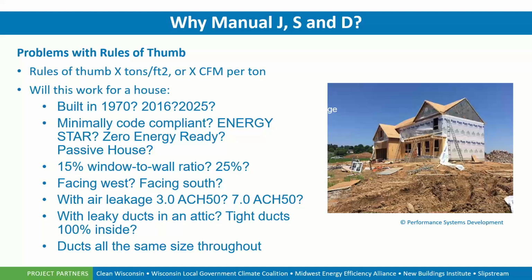Making sure that our ducts are tight, as we discussed earlier. Leaky ducts in attics, if they're supply ducts, we're going to be pushing conditioned air to the outside. If we have unsealed returns in the attic, we're drawing air in. We can be overpressurizing, and we'll talk about that.